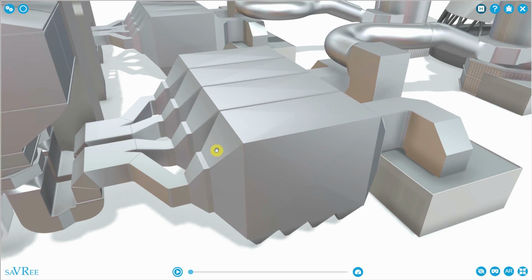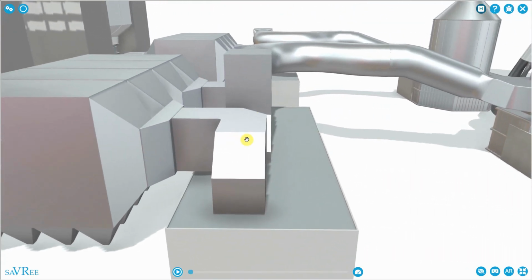We don't want bits of dust and bits of carbon being expelled into the atmosphere, because if that happens, those particulates are going to gradually come down, land on fields, on people's houses and things like that. So it's the electrostatic precipitator, or the ESP, that prevents this happening. It separates the particulates out from the exhaust gas stream, typically with an efficiency in excess of 99%. We've then got a fan. This is an induced draft fan. We're going to induce or draw the exhaust gases from the boiler.